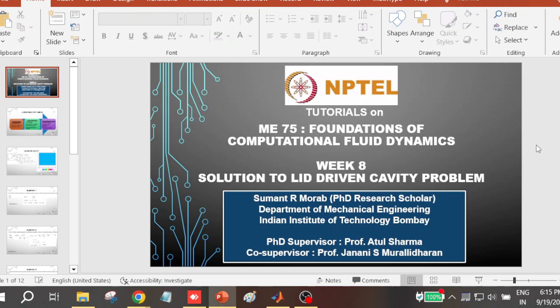They are mostly applicable for many of the problems. But we also saw that when the system becomes tightly coupled, say for example you have conjugate heat transfer, you have natural convection in your problem, then the momentum and energy equations are tightly coupled there, so you get a lot of elements in a row of a matrix. In that case, the matrix is not a penta-diagonal matrix. For a 2D problem, usually you have 5 elements, okay.